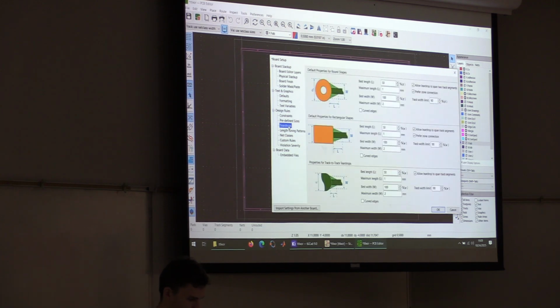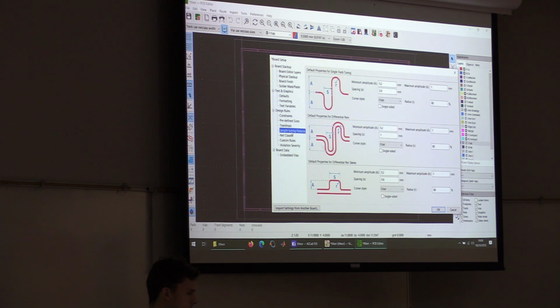And then teardrops. Oh, this is new. I haven't looked into this, so I'll let you guys explore that. This is usually to create a bit of a copper area between your trace and the circle to prevent sharp edges. It's very useful for higher frequency applications, but I will leave that as is.